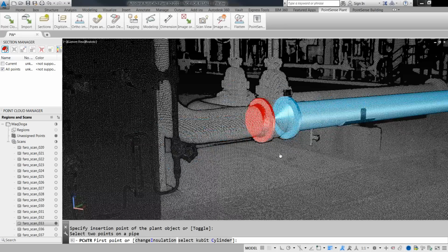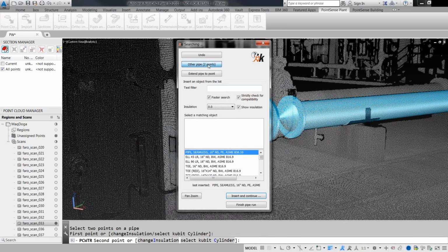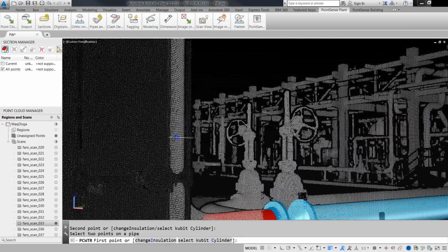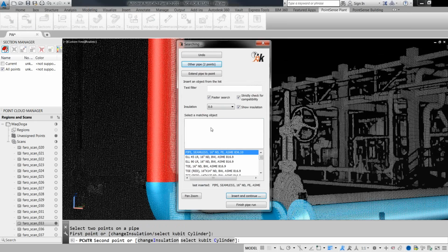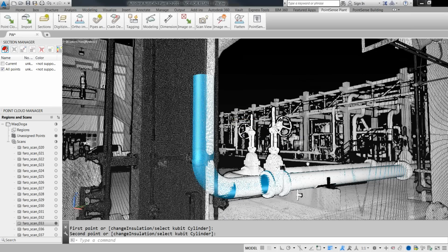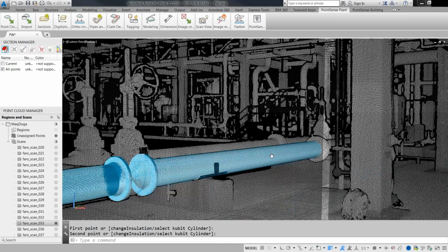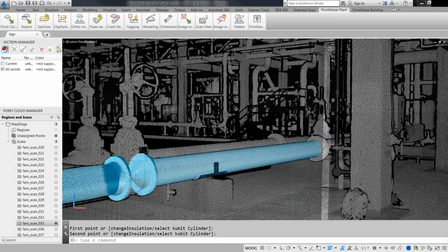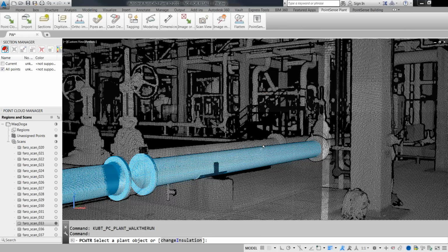So in this case, I'm going to put in a pipe, 2 points, and then other pipe here. You see I can just skip the elbow, just tell it we're going this way, and continue like that. So, I'll finish that pipe run right there, and then if I wanted to continue in the other end, I can do that as well, and in that case, I can do back of face. So let me go ahead and just do a continue off of this pipe,